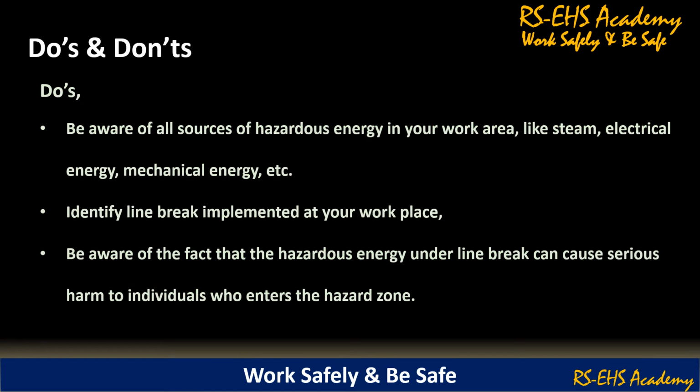Line break process do's and don'ts. Do's: be aware of all sources of hazardous energy in your work area like steam, electrical energy, mechanical energy, etc. Identify line breaks implemented at your workplace. Be aware of the fact that the hazardous energy under the line break can cause serious harm to an individual who enters the hazard zone.